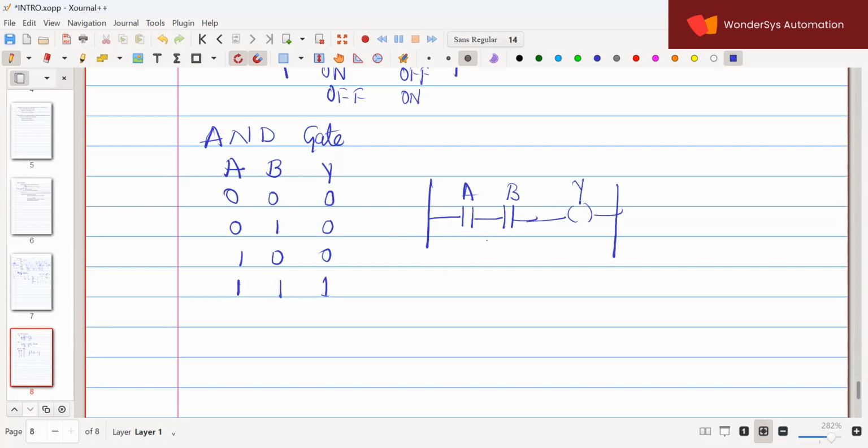That's why. Okay, in parallel condition also, if I connect and both the inputs are high, the output will be high, no? That one is for the OR gate. Why not parallel? In parallel, if you switch on one, the output will be on. Correct. So in a parallel combination, if any one switch is on, the output will be on. Therefore, whenever we are realizing the AND gate, we need to connect the switches in series fashion.